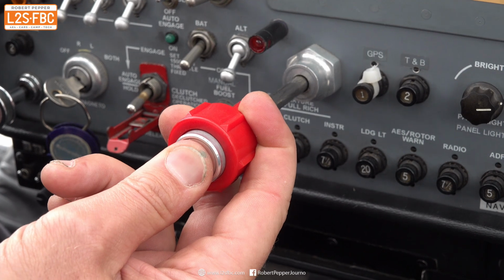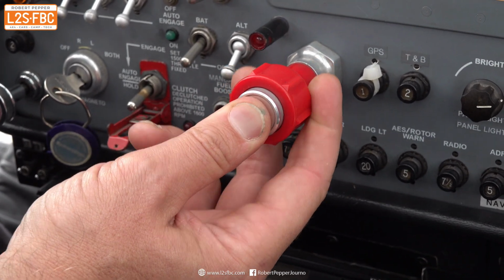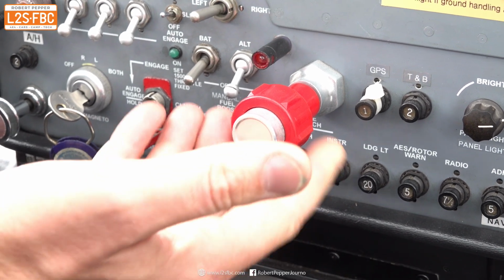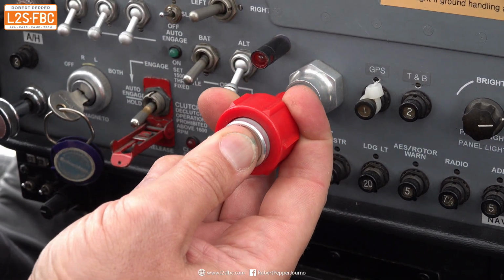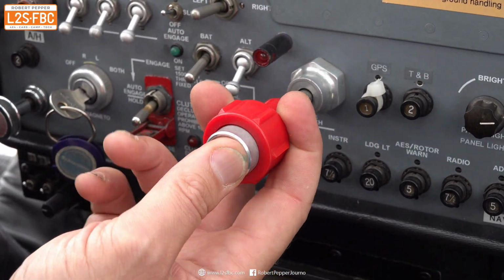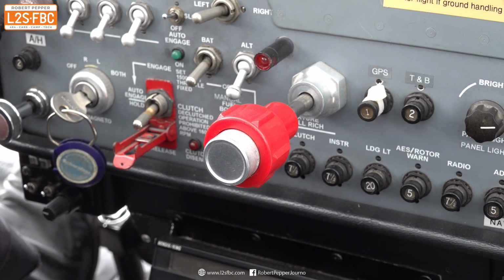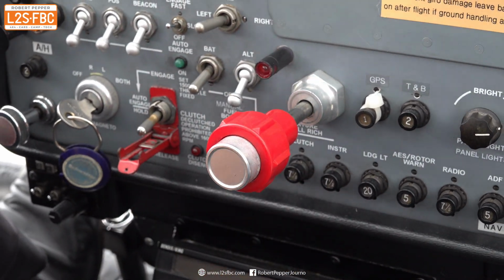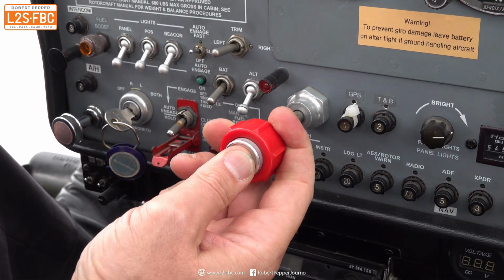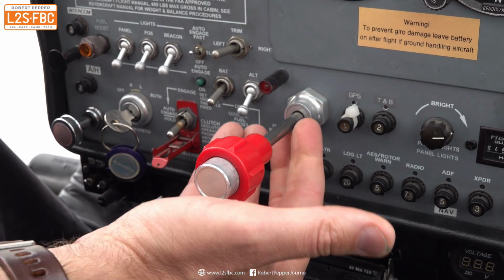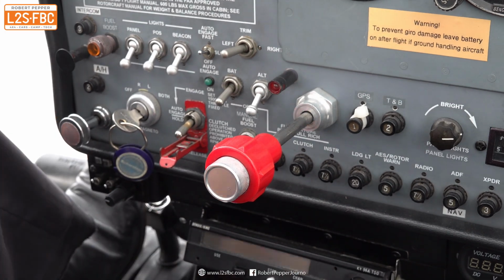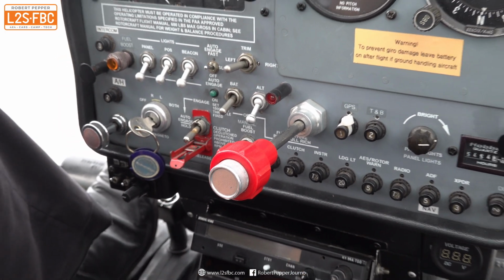In fixed wing, because you have a different dynamic, they leave it mixed or rich. This is how we start it, but then they start to lean it as they climb out, because the air becomes less dense. But in a helicopter, because we haven't got a propeller up at the front, if our engine stalls, it's very unlikely that low to the ground we can restart it again. So in this model, we never apply a mixture lean. And then, yes, you've got power, so the engine is running.